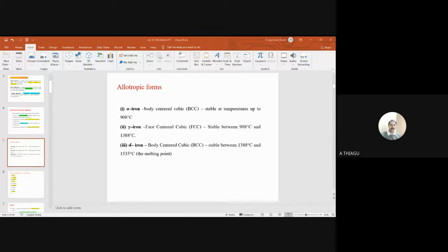So iron has a very limited 0.08 percentage of carbon only, whereas in the case of steel, the material ranges from 0 to 2 percentage. It comes under the steel category. Then 2 to 4.7 is the maximum weight percentage of carbon involved. So it comes under cast iron. Cast iron has more weight percentage of carbon, but the property changes from ductile to brittle. Please keep in mind. For steel, you can give many examples: steel rods, construction material, shafts, it all comes under steel.